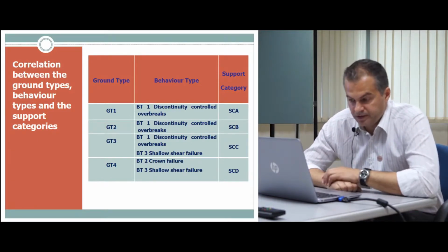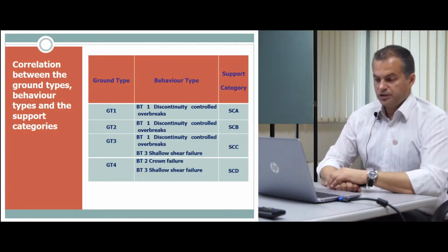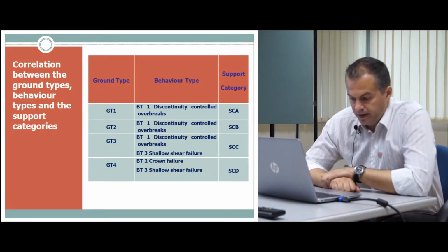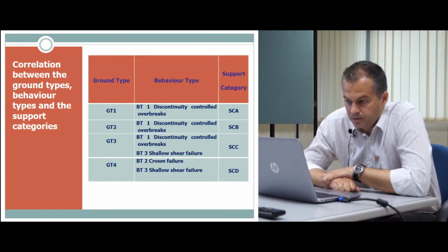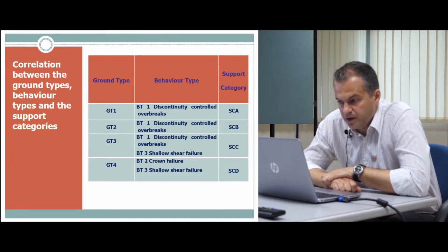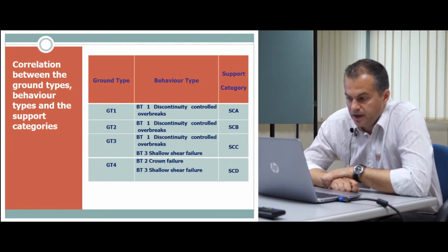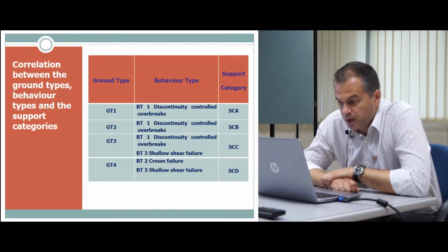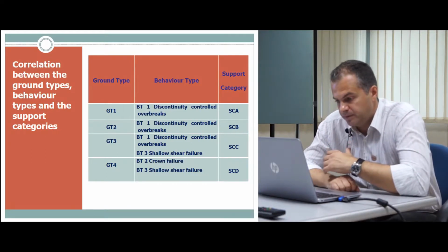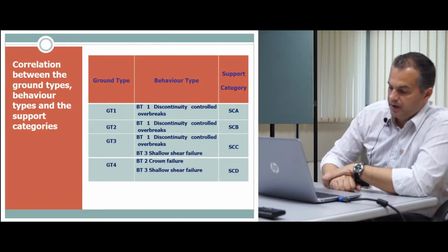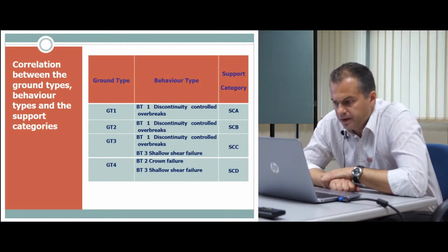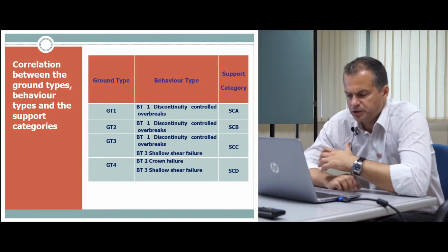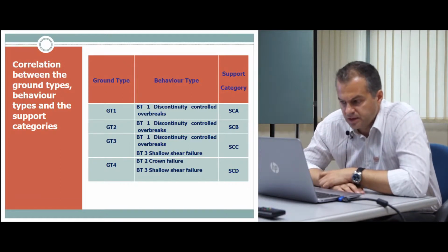So starting from the first case, just in order to contain these wedge failures, you need some thin shotcrete, not very thick, reinforced of course, and Swellex anchors, because you have the siltstone layers, you have this immediate wedge sliding and falls. No steel ribs would be needed here, and a larger excavation round could be implemented.